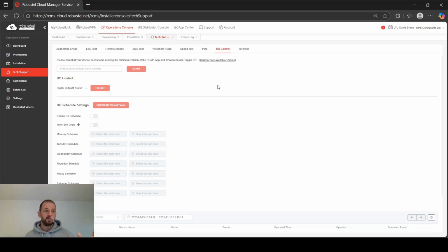For many years, Robustel had digital inputs and digital outputs, but they're only really useful if you have some nice overlay, nice simple interface to make the tool useful. And there is actually a document that is available in the support section. It shows how you connect the digital output that is being controlled, scheduled in this way, through a solid state relay. That solid state relay can then switch anything from a small DC device up to bigger mains loads.